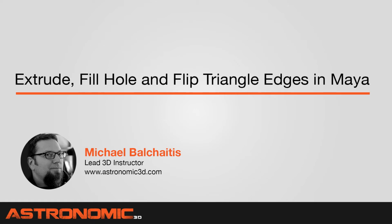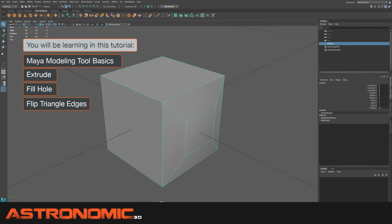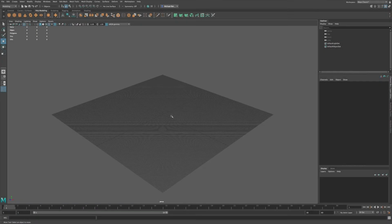In this Maya tutorial, I'm going to talk about a few modeling basic options and commands that we have. What I'm going to talk about is the extrude, fill holes, and flip triangle edges. You can add polygons to an existing mesh by extruding polygon faces, edges, and vertices using the extrude command.